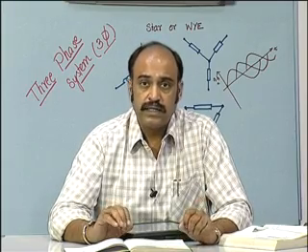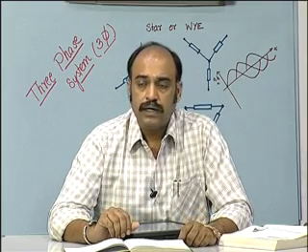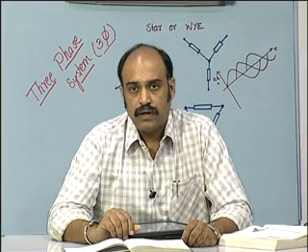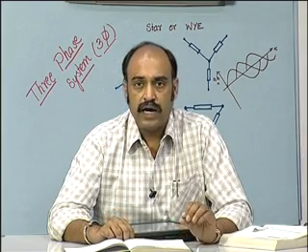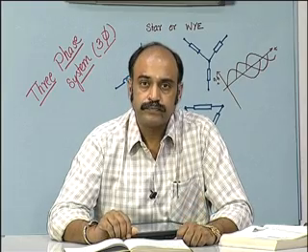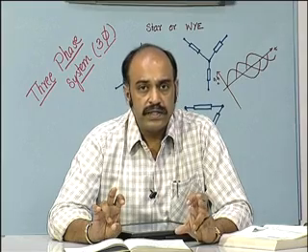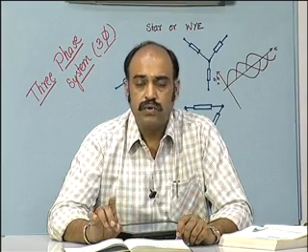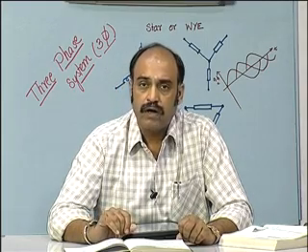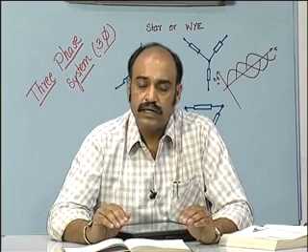In the case of the delta circuit, we discussed one important unbalanced load condition, and that is, in the extremity, if we had only one single resistor as a load. Then two of the lines will have currents in them, that is, one will have a forward current and one will have the return path current of the resistive load. The third line will not have any current and it will be just open.